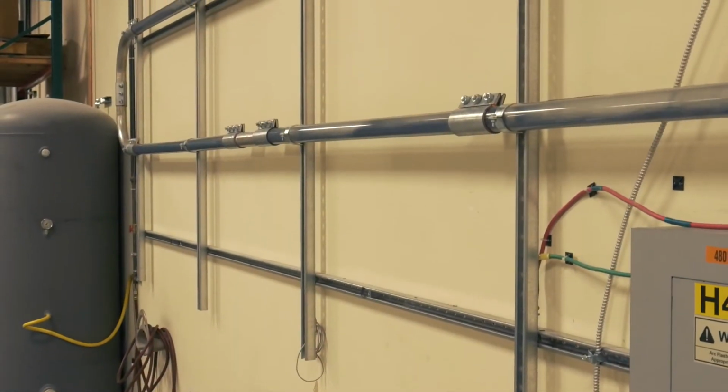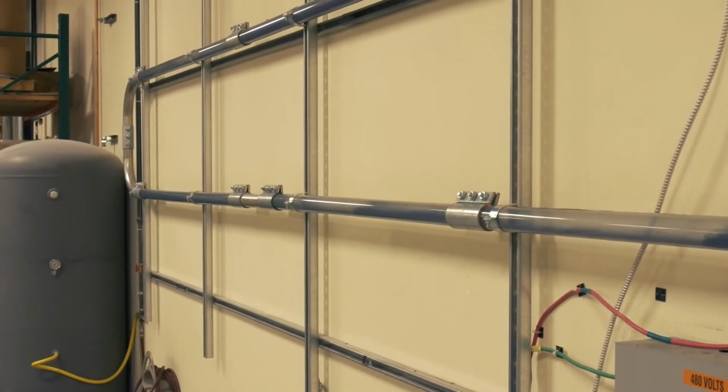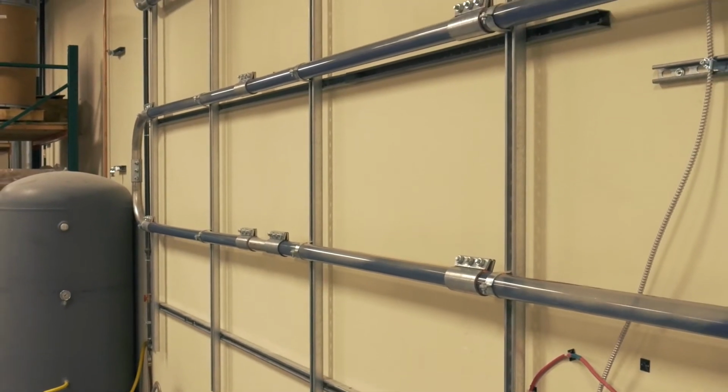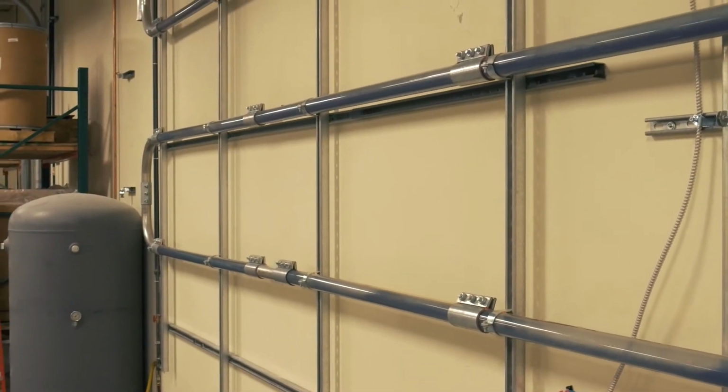Attrition and erosion are directly proportional to the velocity of the resin to an exponential degree. Attrition is the breaking down of your pellets, with respect to dust generation or angel hair, and erosion is based on system components. If you're conveying glass-filled nylon, for example, and you're wearing through elbows or receiver bodies, that's because you're conveying that resin too fast. You do not have to have your system be within the dilute phase of pneumatic conveying. You can implement wave conveying to slow that resin down and still make rate at your receiver.